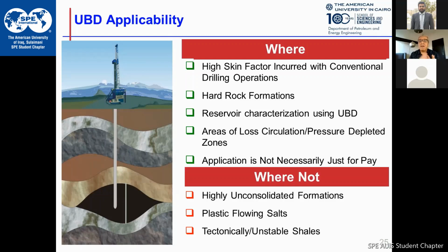And of course, there is other technology associated with underbalance. So we need to see our reservoir before we approach the top of the reservoir. Different techniques exist. For example, when we get closer to the reservoir, we can use gas chromatography, GC units, okay? And a GC unit does analysis from C1 to C6, along with some sour gases. And now we plot different ratios, and when these ratios cross, they tell us that we are almost 50 or 30 or 40 feet above the reservoir. So we get some guidance by the use of technology in order not to miss.